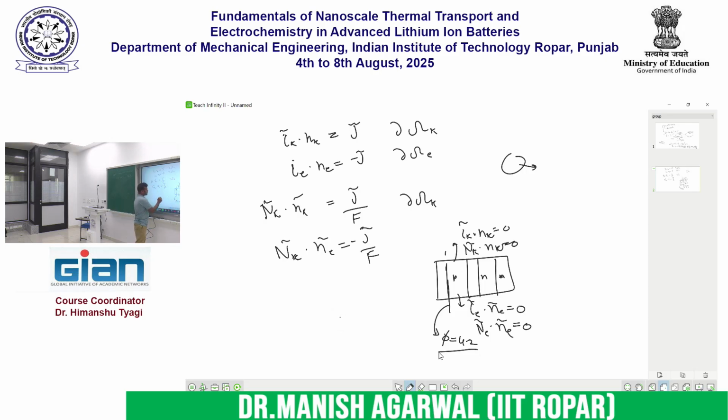Then you will prescribe the total current at this boundary, which is going to be del phi dot n multiplied by sigma_e, and you integrate that over the whole boundary, and this will be equal to the applied current, I applied.